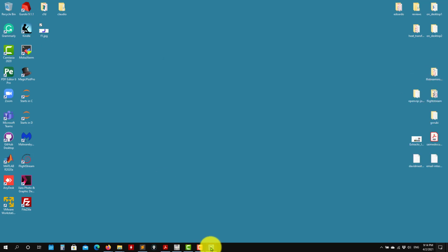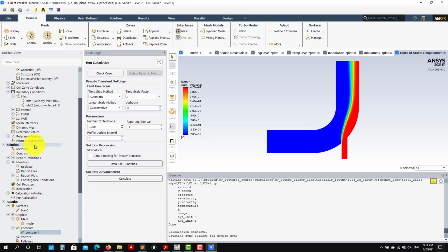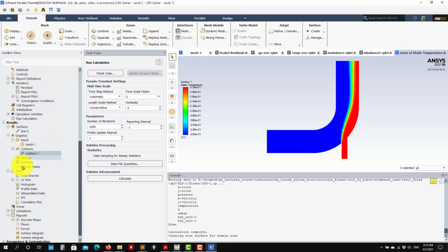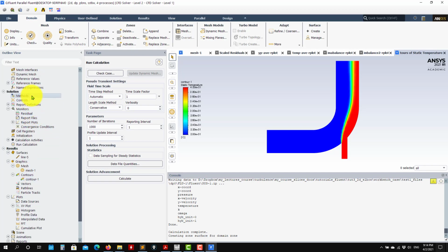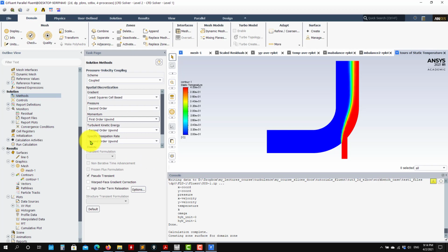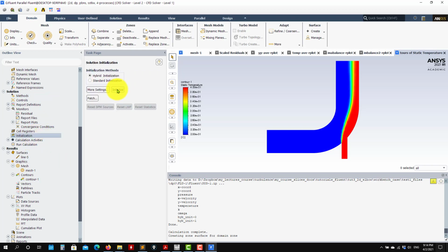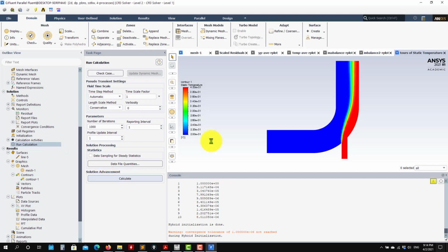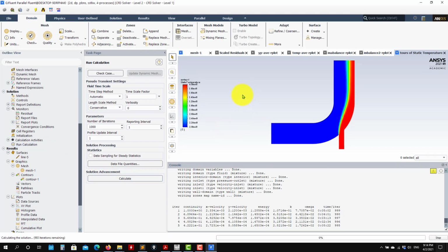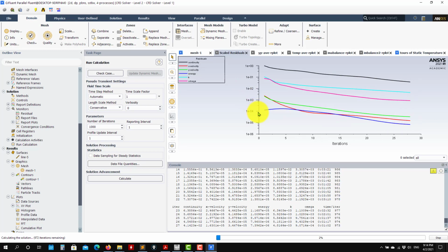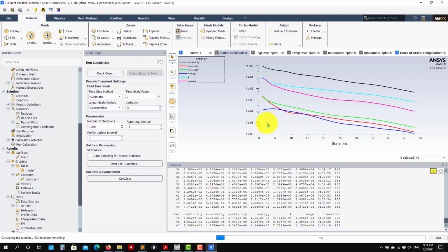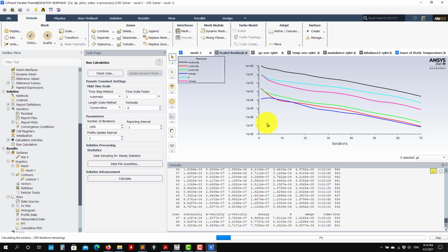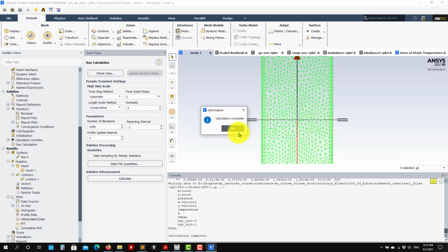And let's rerun this case just to show you the difference when you run with first order accuracy and what is the problem. So now let me rerun. Remember, the only thing that we need to change is the discretization here in methods. So now if I go here, first order accuracy, and let's start from scratch, from 0, and calculate. So now we're using a different method to approximate the convective terms in the momentum equation. So see that convergence is very nice. Like the previous case, we have a solution.